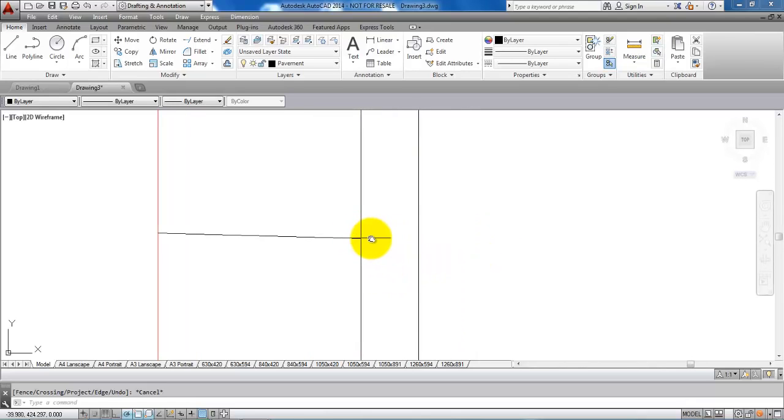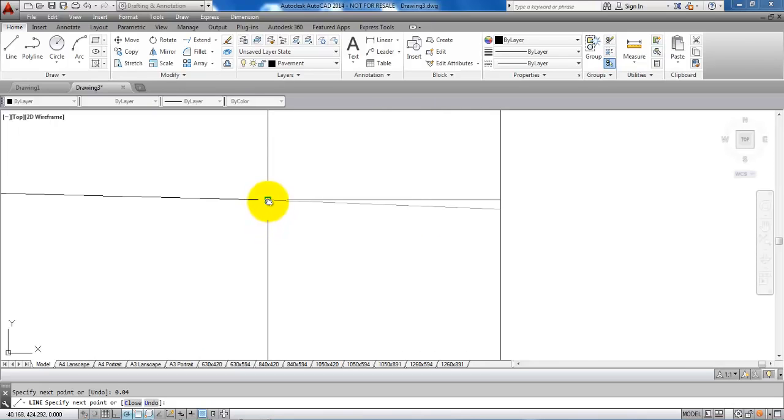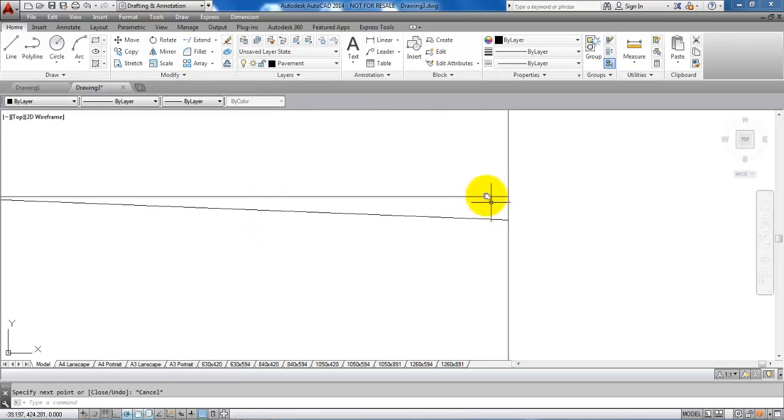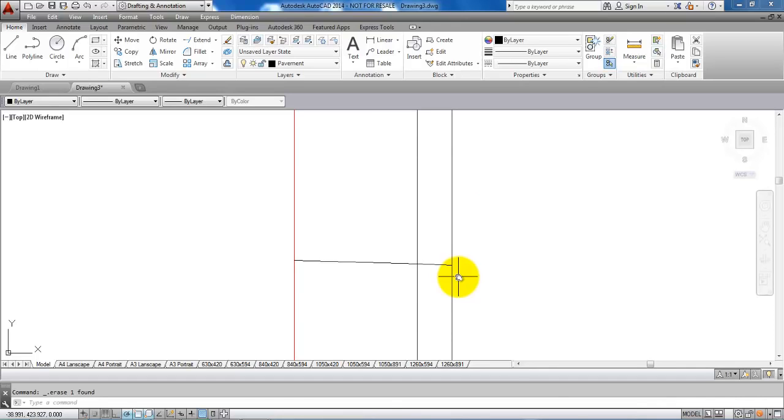And for the shoulder I want to have a slope of 40 per mil. So again I will type in L for line, draw a line of 1 meter, and this one should be 0.04 and hit enter. And I can just draw the line up here and delete this line and also this one right here. So now I have the correct slope.